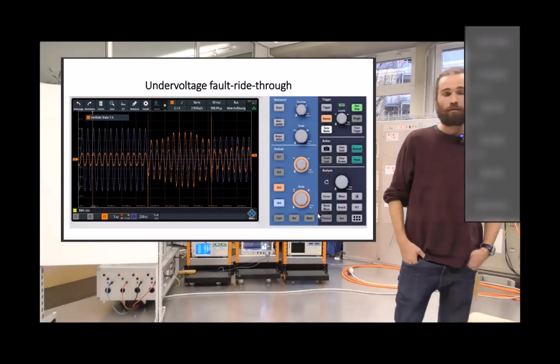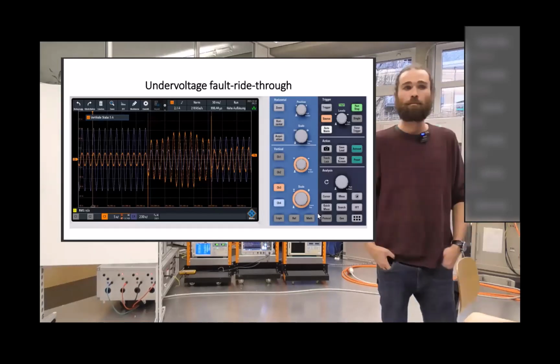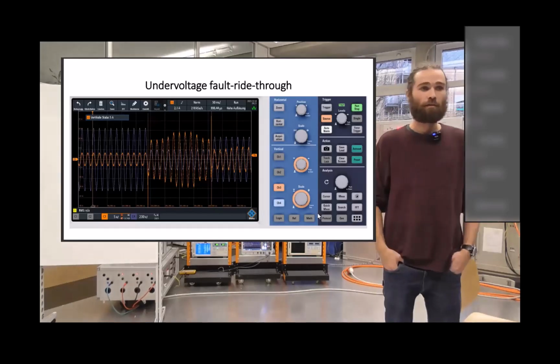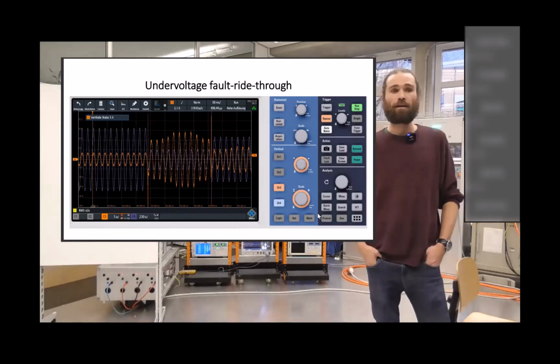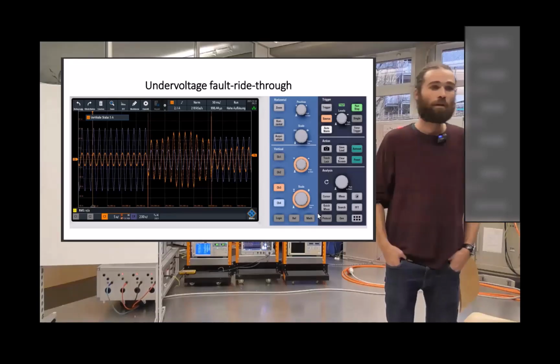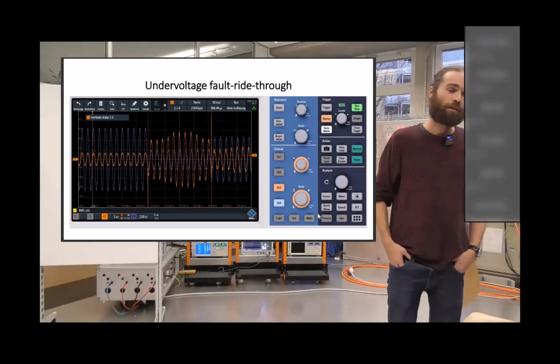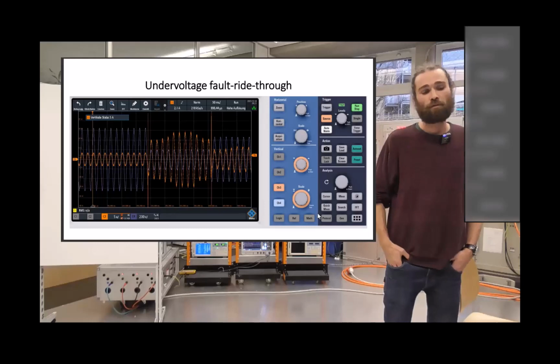This is quite difficult to get in the live display. That's why we have it in presentation. It's the same situation. The blue line, which represents the voltage, went down to 30%, and the inverter then tries to increase the current such that it can bring the power into the grid. That's quite difficult at that low voltage. But as you can see, when the voltage came up again, it had really fast again, the current should have to inject the power to the grid.